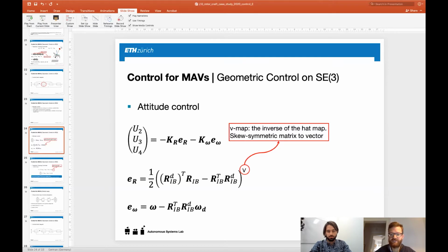Regarding advantages and challenges using MPC, this is not so easy to answer directly. So there's different methods on how we can use MPC, so model predictive control for MAVs. So we can use it on a high level to only create paths that we want to track. And then it's okay to only update with a low rate, so only with 10 Hertz or 5 Hertz or something like that. And in that case, it works quite well.